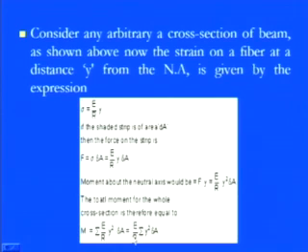E and R are constants, as we discussed. E is the modulus of elasticity, which is a property of the material you are using, so Young's modulus will come in, and the curvature is the dimensional parameter. If you take those out, we have the summation of y square dA, which when you sum up the small elements gives you a real feeling about the moment. Once you do that, you have the total moment for that section.